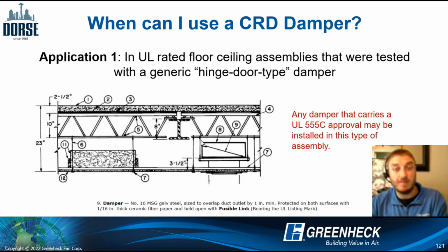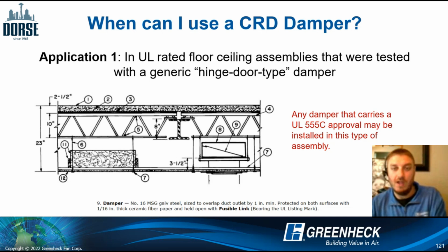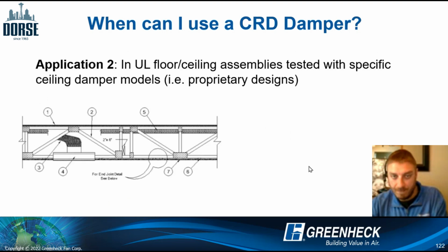So if you see something like this where there's a generic description of a damper, any UL 555C classified product may be used in this type of a design. So this is kind of your free-for-all. If you're qualified to UL 555C, you can put your damper in these types of designs that just have a generic description of a damper in it.